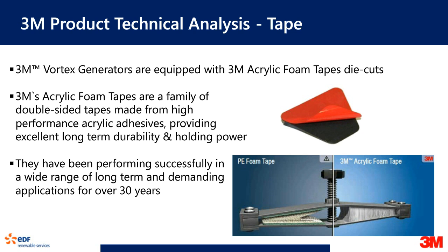And we quickly learned that the stronger the adhesive you apply, you actually have a lot of challenges in fatigue. Why is that? When you look at a blade, our blade has a lot of flex. And also, our blade has surface tension because of the stresses and because of the flexes. To make things more complicated, you have a composite surface, again, epoxy or polyester, carbon fiber versus glass fiber. So you have a lot of different coefficients of thermal expansion on a blade itself, and then you have the surface forces. Then you apply a vortex generator.